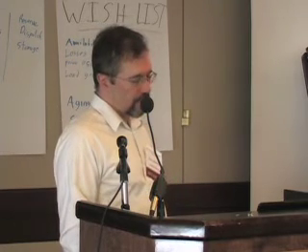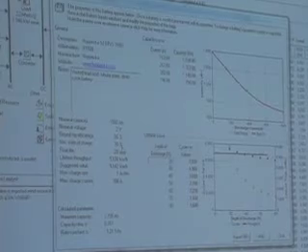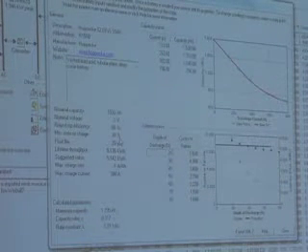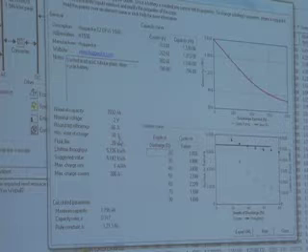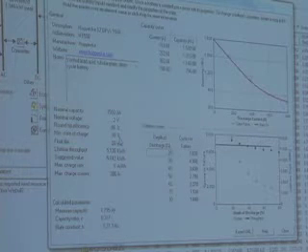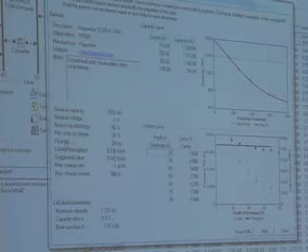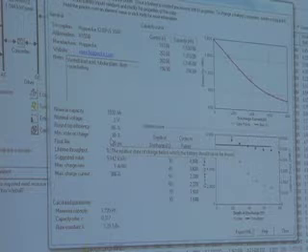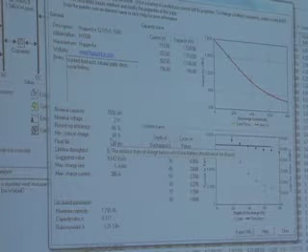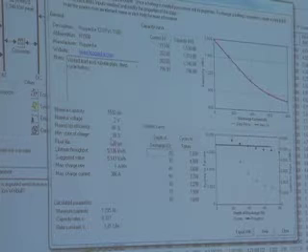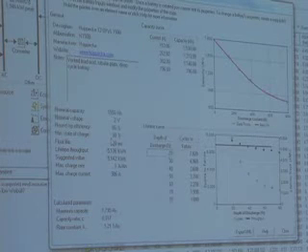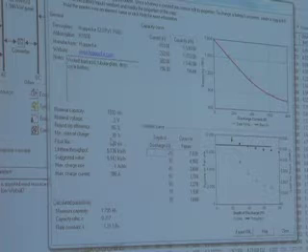If the way we deal with low states of charge is we enforce a minimum state of charge here. Now, one of the things that we're going to change in HOMER, because we've changed it, this is the way it used to be quite a while ago, we changed it and we decided we liked the old way. Right now we treat the minimum state of charge as a property of the battery. If you want to change the minimum state of charge, it's really an inverter setting. It's not really a property of the battery. So my apologies. For now, we're treating it as a property of the battery.